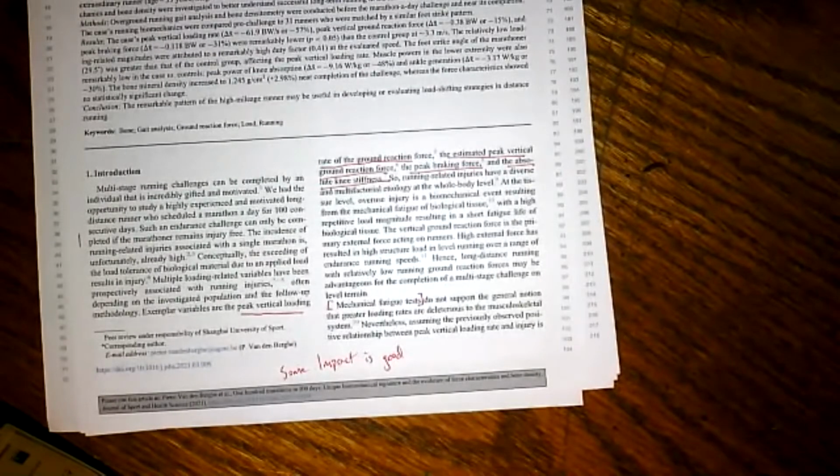And what you do is you put that material through some fatiguing protocol or some repetition. And the fatigue protocol ends when the sample breaks. You can put it under tensile load, you can put a compression load, you can put a torsional load, all these different things. And you wait and you do lots of measurements up until the material fatigues and fails.